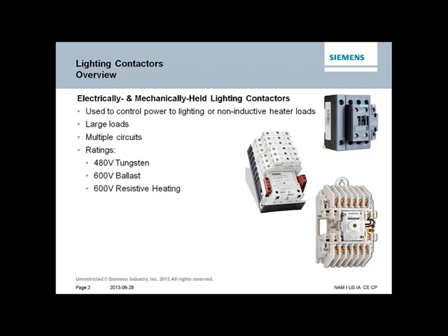Lighting contactors can also be used up to 600 volt resistive heating applications. Resistive loads differ from typical inductive or motor loads in that there is no high inrush that you would normally see in an inductive load. Our lighting contactors are rated from 20 through 400 amps.